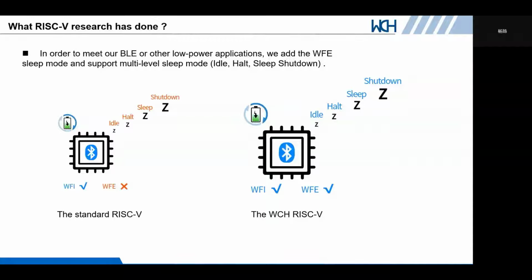WFE is more advantageous on some occasions because in some application scenarios, we only need to wake up and execute subsequent events directly after wake up. Compared with WFI jump interrupts, it has higher real-time performance. RISC-V currently does not support multi-level sleep mode, which is not conducive to low-power applications adapting to different power consumption and performance levels.